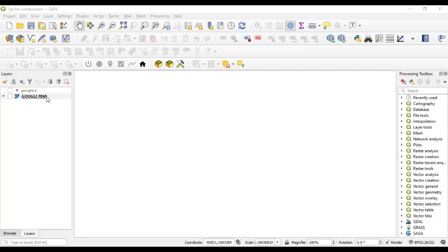Okay. Now before we talk of digitizing those points, we have to learn how to create a point, line, and polygon. Okay, which is one of the functions or one of the topics of our class today. Okay, so now how do we create points? Because you see the first task I did here in bringing the CSV to QGIS, I actually went to add layer instead of creating. The reason is because I already have that data somewhere, so I'm bringing it in. So when you have data somewhere and you are bringing it in, you use add layer.